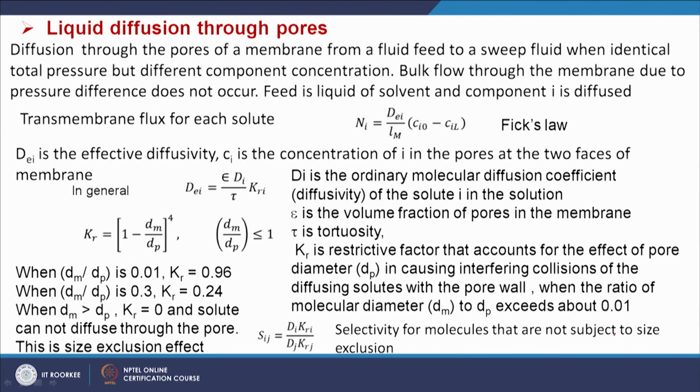Now, we will discuss liquid diffusion through pores. This is diffusion through the pores of a membrane from a fluid feed to a sweep fluid when there are identical total pressures but different component concentrations. Here the pressure difference is not there, only the concentration difference is there.